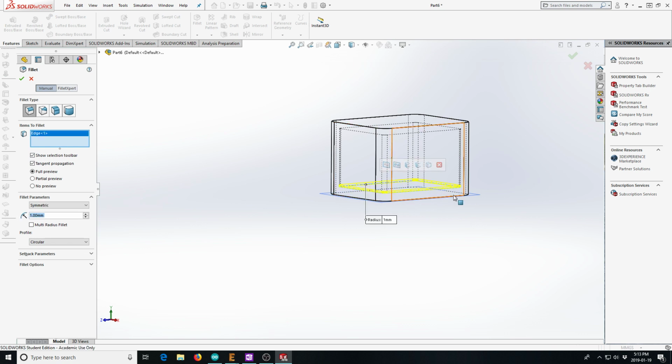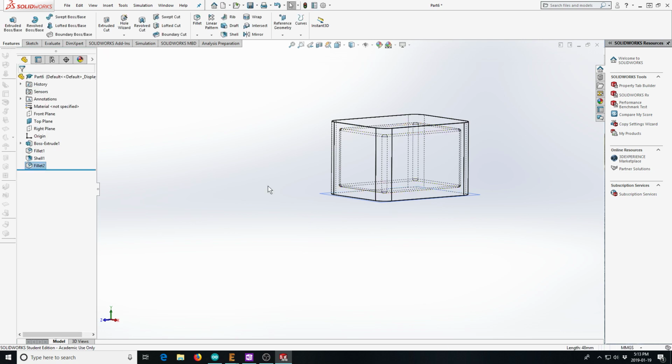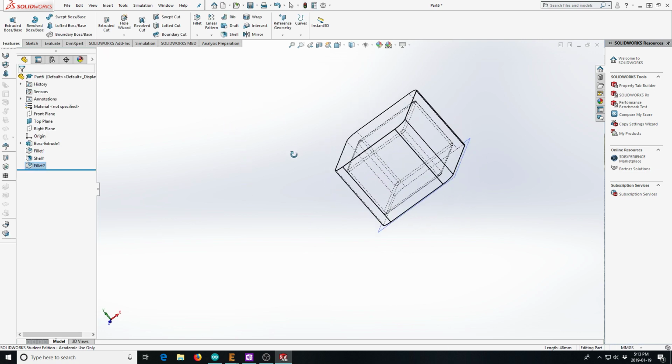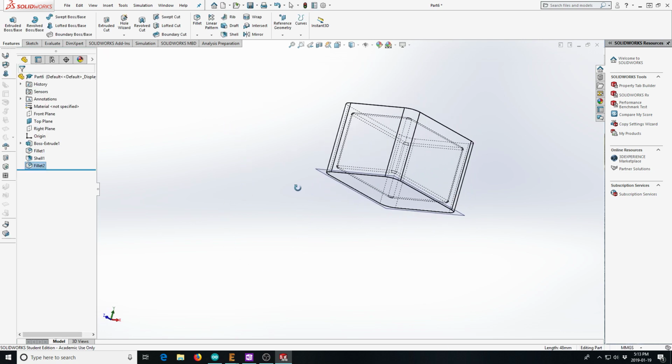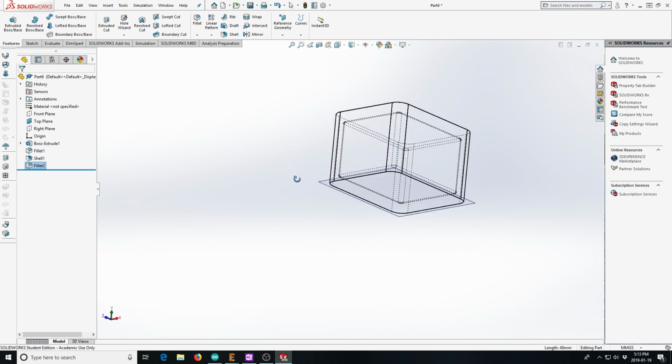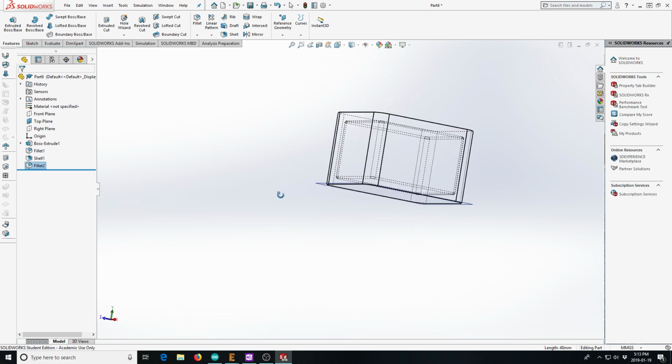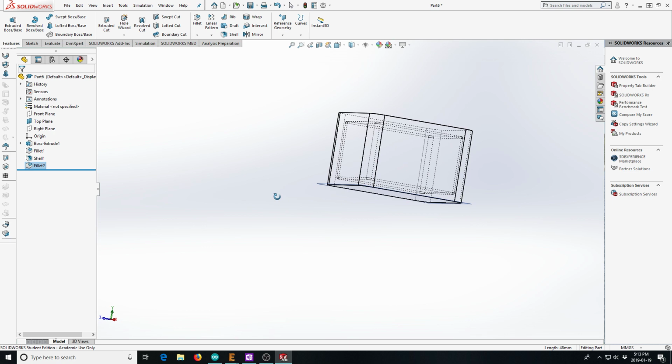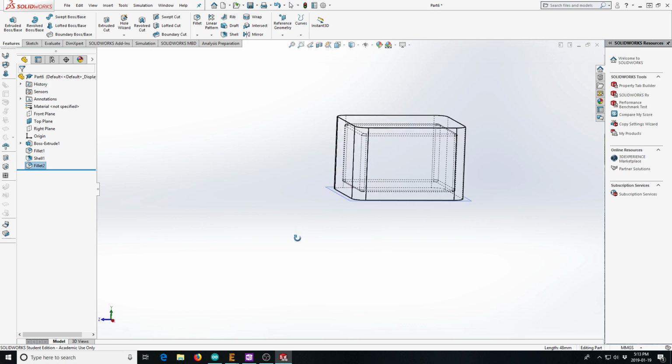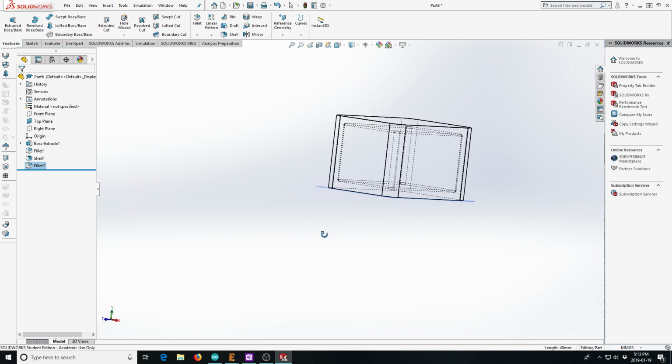And notice it's smart enough to try and pick the entire loop. I'm going to pick that one. There. So when I go to 3D print this, it will 3D print with those nice radii on the inside. If I was making this on a CNC milling machine, then there could be a tool for the milling machine to actually cut those fillets. In general, that makes a better result.